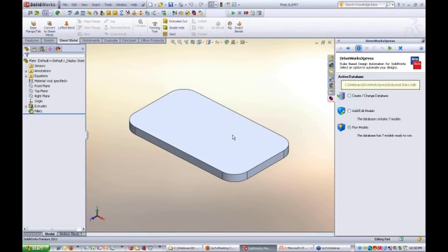I want to automatically have the thickness of the plate set to be 1/10 of the width. And I want the rounded corners or the fillets to be optional. So I can choose a sharp-edged plate or a rounded corner plate. Okay, so remember I said you have to have created the model first before you can drive variations of it. So before, when we were running the model, that was because you already had the database existing. This time I shall create a new database.